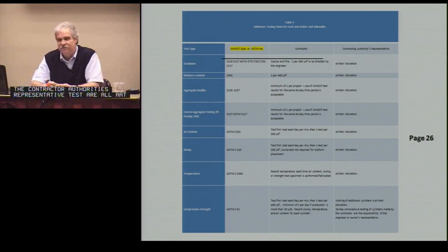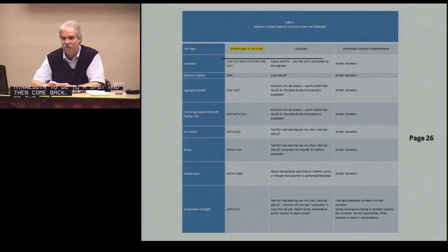The intent was, I mean, some of the consultants tell me they've been building some old TV towers, I should say cell phone towers, around the state. And then they got to send a technician out to meet the ready-mix truck and run their one test, and then done for 100 yards, a 60-yard tower, just once every 100 yards. In this case now, the engineer could use this specification and require the contractor to bring somebody certified to run the test, instead of running this technician 2 hours out in outstate Minnesota to go to a spot and then come back. So that's one of the places we think this spec can be used.